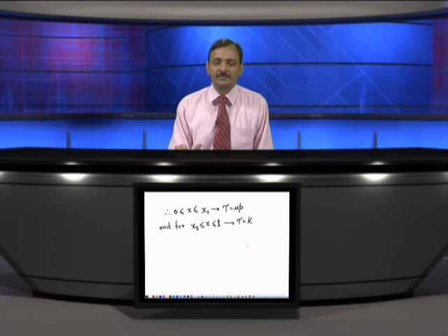For the sliding one, we take whatever force is applied from the top times the coefficient of friction, and for the sticking zone, it is from the dividing point up to the middle. So we have two zones.